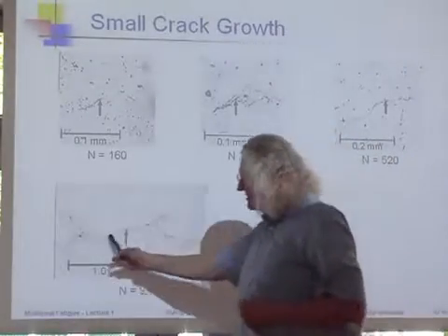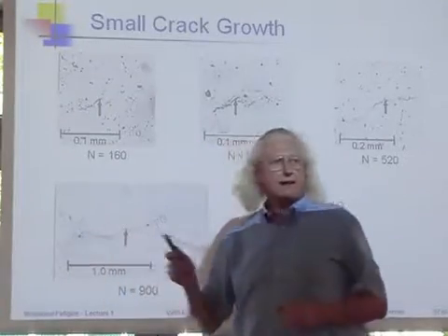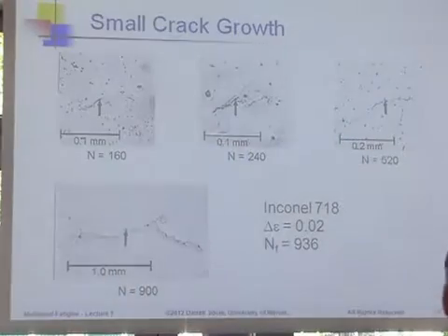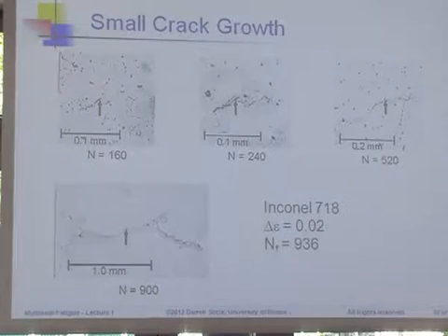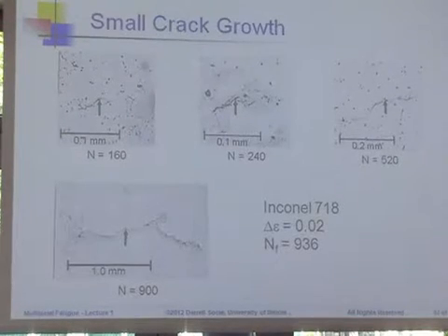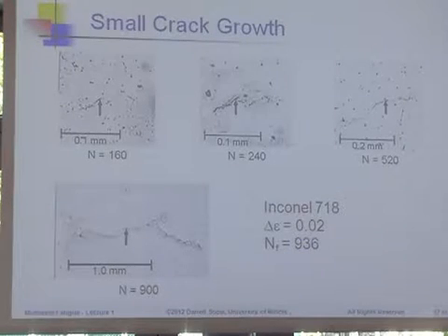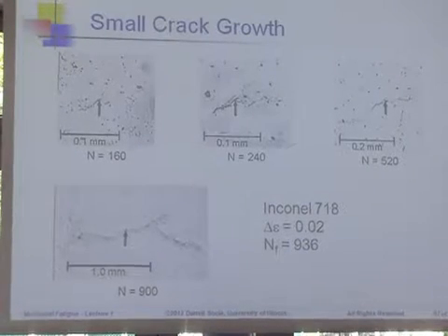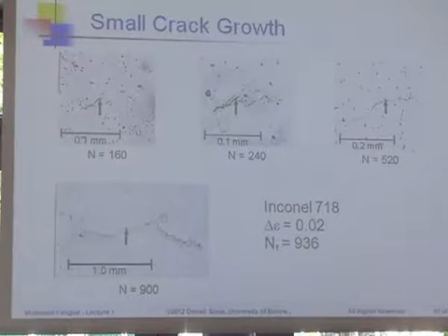Or I might try to model this stuff where the plasticity that comes from this is driven by the crack tip. How could a single fatigue model ever work? When I just showed you easily now 3 different sets of physics. Right? I can find a model that works really, really well in any of these 3 regimes. Right? But I can't find a universal model that works.